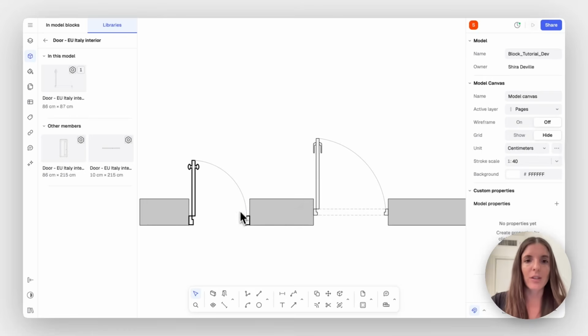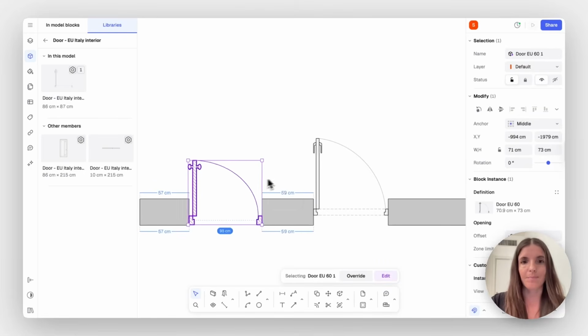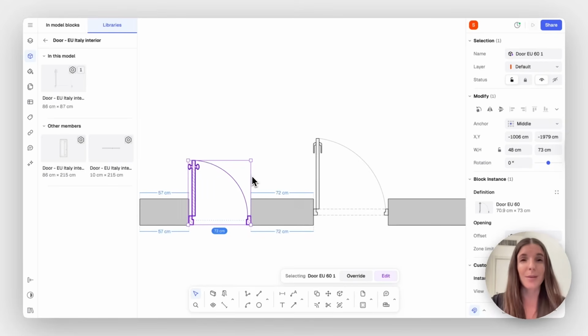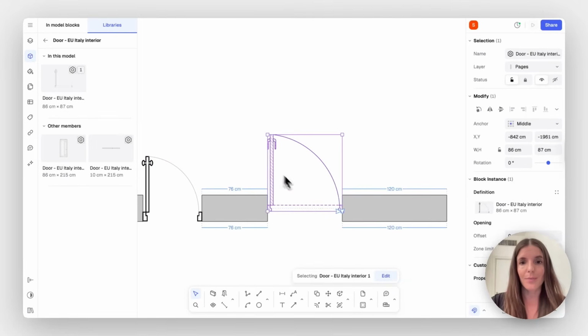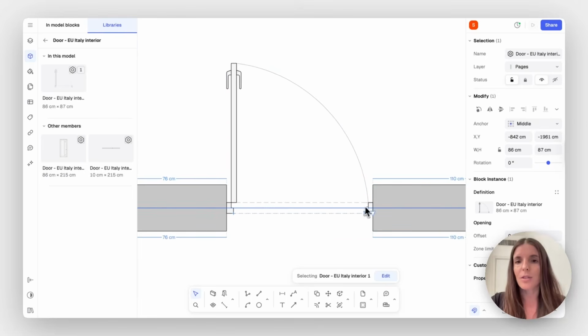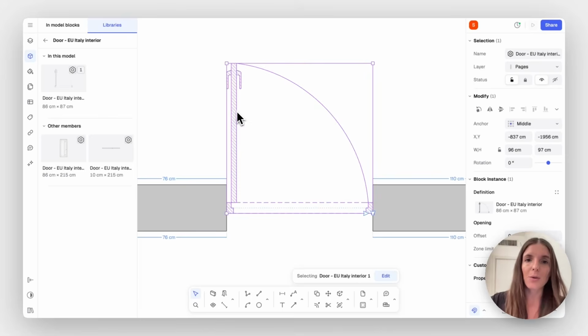For example, if you want to change the opening width of a door and you try to do it with a single block, if you just toggle on it, you'll notice that the door gets completely distorted, its fold doesn't get longer, so it's not really useful to us. In a parametric door, however, once you select it, it will hold this arrow, which will give you a few standard options for door sizes, and will automatically shift the fold accordingly and give you a nice complete block.